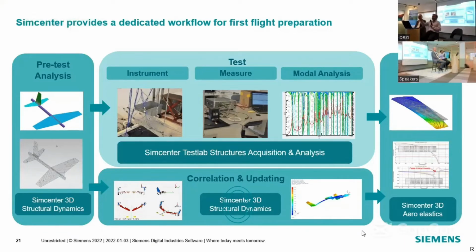It is going to have an excitation at that particular edge, or in the middle of the wing, or in the middle of the propeller. Based on that, you can determine the number of sensors and accelerometers, and you can virtually place them. Then you can use your shaker to shake and see how this drone is matching your simulation results.